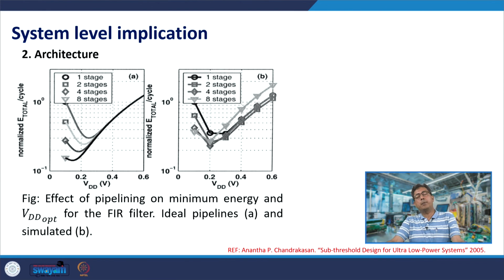If you increase the pipeline stages, then logic depth reduces, and because logic depth reduces, therefore, the optimum VDD, since leakage energy reduces, you can reduce the time period, that is increase the optimum VDD, and the dynamic energy increases and the optimum VDD increases.